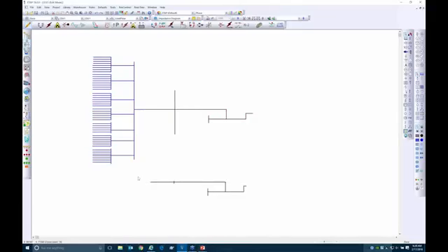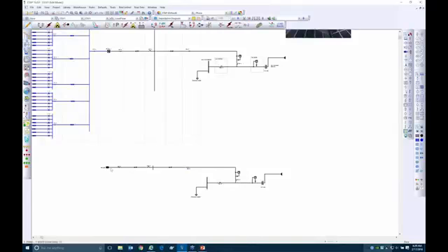And there's another system down here, which is taking the entire DC system, making it equivalent into a single source, and I have the entire AC network. So if I was doing grid interconnection studies, I would be using a single source generation, single PV source generation, and then modeling the details of the grid on the right-hand side. And my main focus would be to see what happens in the grid when I have PV in my system.